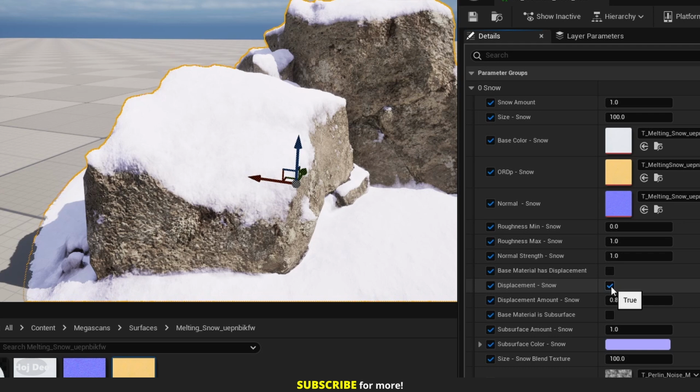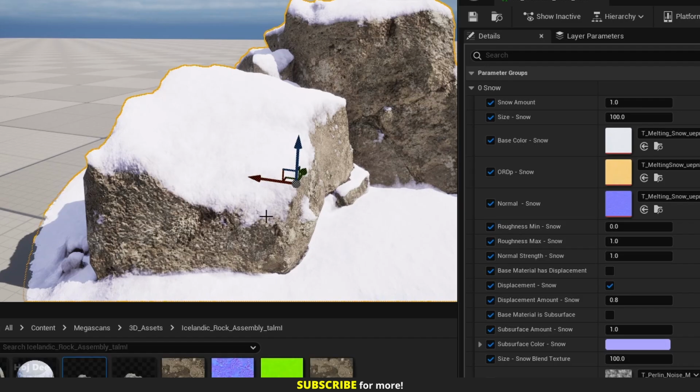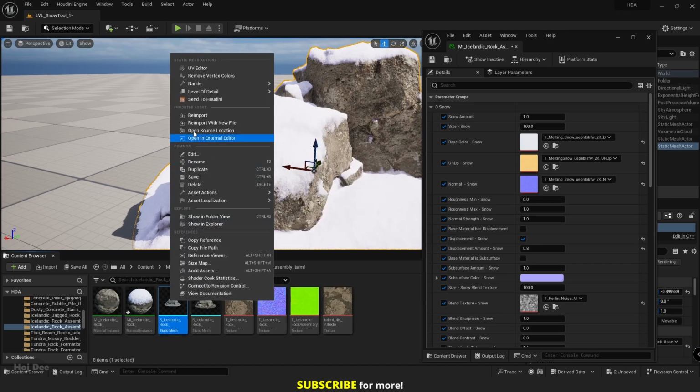Now right now displacement works for me, but if it doesn't work for you, make sure that Nanite is enabled for the mesh. To do that, browse to the mesh, and for that select the mesh in the viewport and press Ctrl B to browse it. Right click on it and under Nanite make sure that it's enabled.